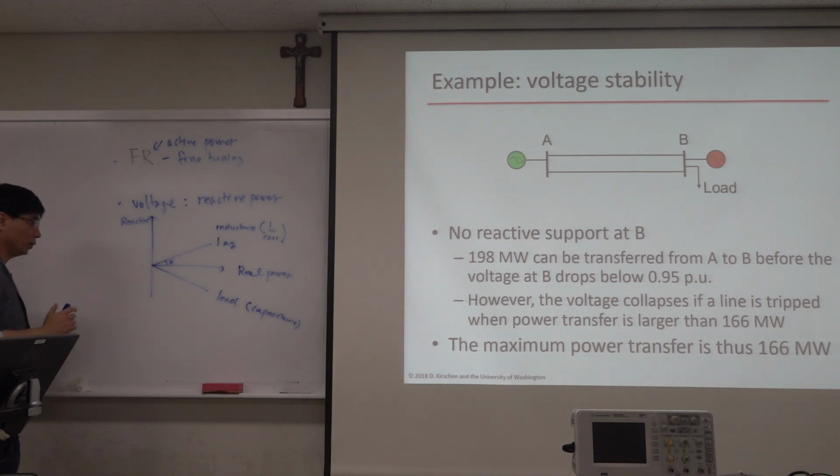So when you are confused, the meaning of lagging and lead means that we have a resistance, we have a coil, and we have a capacitance, either serial or in parallel. Anyway, so R, L, C. Then we have a current, I. Okay. Then, using phasor notation, the impedance is R plus J omega L plus 1 over J omega C, right? So when the current is common, the current is common for RLC because we have this serial connection here, okay?